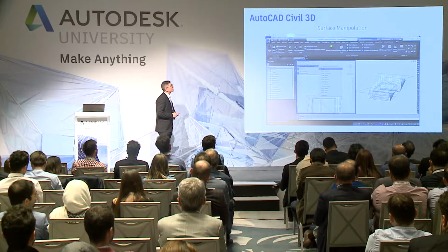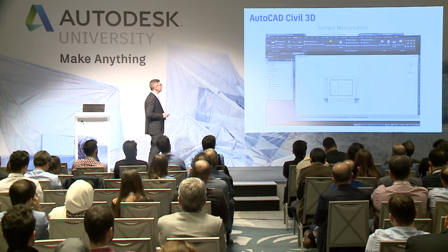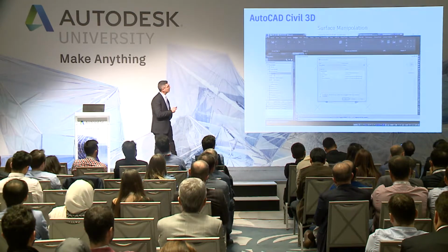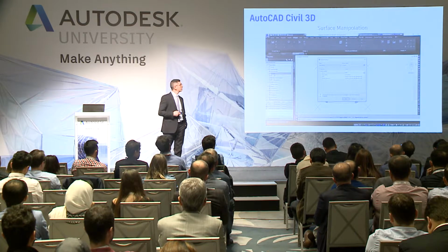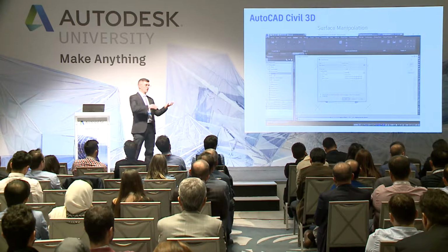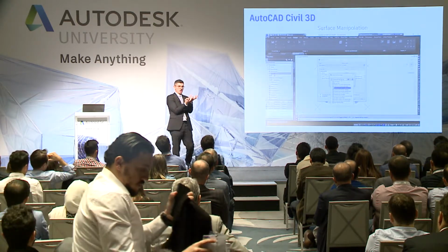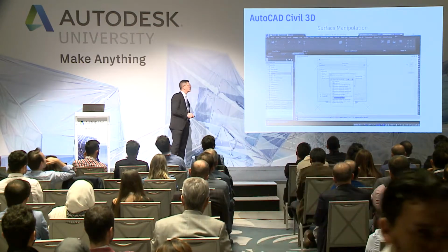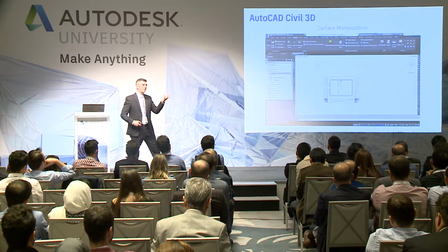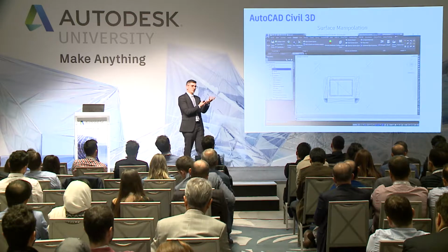We can also manage the surface, because sometimes we need to change something. What I mean by managing the surface is that I want to create the final surface, the surface that is the terrain with the hole of my excavation shape. Then I need to create a new surface, like an empty box. And inside this empty box, I can add the existing ground and the excavation surface.